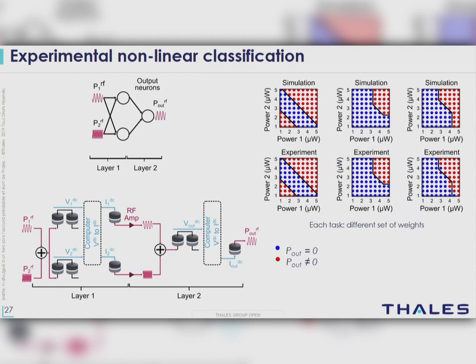And so what you need here is this DC voltage converted to a DC current. This we just measured from the voltmeter and injected with the source current. So here we were going through the computer. But in a real system, and now we are building a CMOS integrated chip with the MTJ and the CMOS, so you need a DC amplifier, which is something that people who design CMOS can do, but we didn't want to do this for the tabletop demonstration.